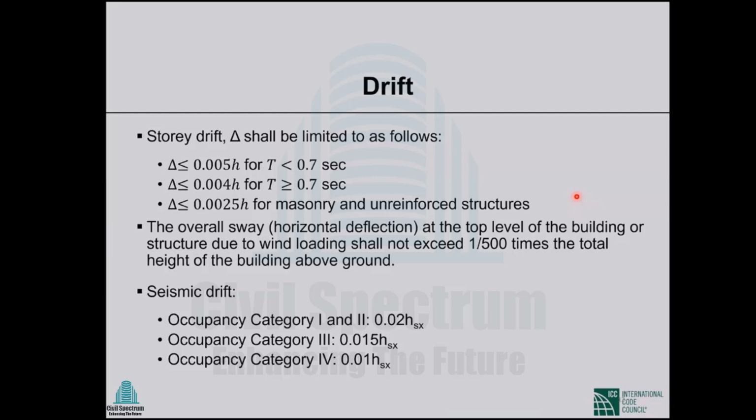Fundamental period is this: if a structure is pulled in one direction, and we remove the pull, then it vibrates, right? Then the time it takes to come back to its original position, or to make one cycle, is called the period of that structure. Very simply, that is the period of the structure.